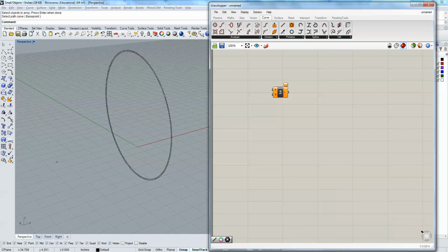Okay, and the way this works is we've got two inputs and then a line comes out of this line engine, and that makes sense because between point A and point B, that's how you define a line. So we're going to define that. So we need to go back to parameters and we need points. So this point here, drag 1, drag 2, so we can get from A to B. And the way Grasshopper works is we connect these A input and B input, and now we just need to define the system and then it will generate itself.